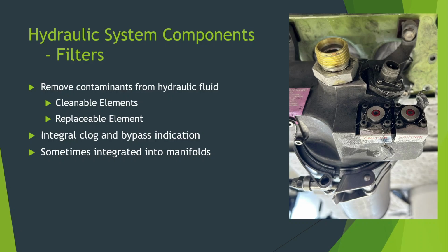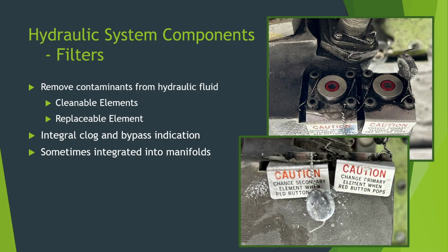This filter bowl cartridge setup originally had two filter elements, a coarse and a fine, and that's why it's got two indicators on it. But that has been replaced by that single element filter that you all saw when you did the lab. So those are the bypass indicators there, what they look like. This is in the set position.